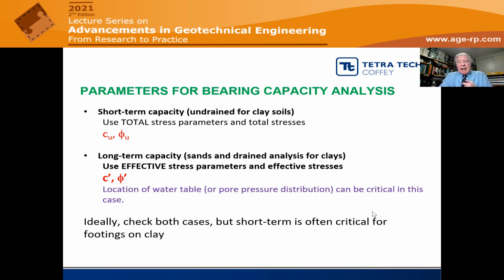Now, ideally, as geotechnical engineers, we should be looking at both cases. The short-term case, particularly for foundations on clay, looking at how critical that bearing capacity is when we quickly load it, and then what that bearing capacity is if the load stays on for a long time. And in general, it turns out that in clays, the undrained bearing capacity tends to be critical. The long-term capacity tends to be greater simply because the soil consolidates and gets stiffer under the action of the load that is sustained over a period of time.